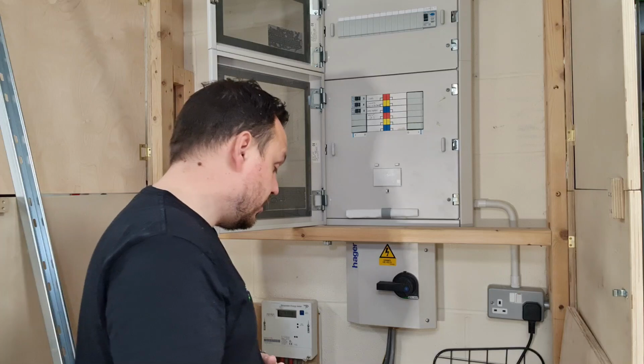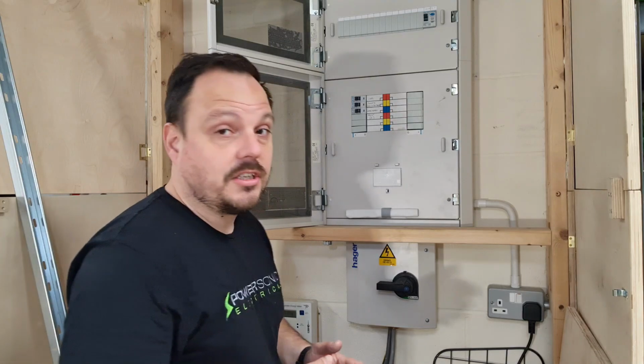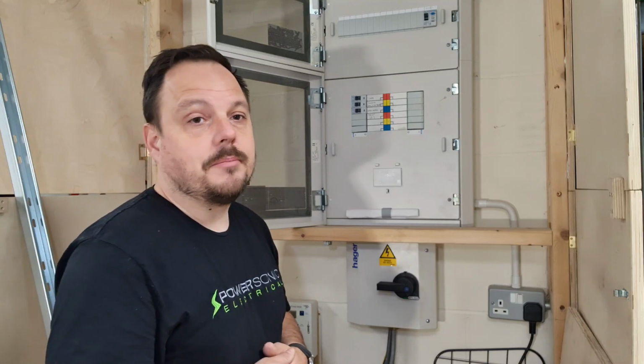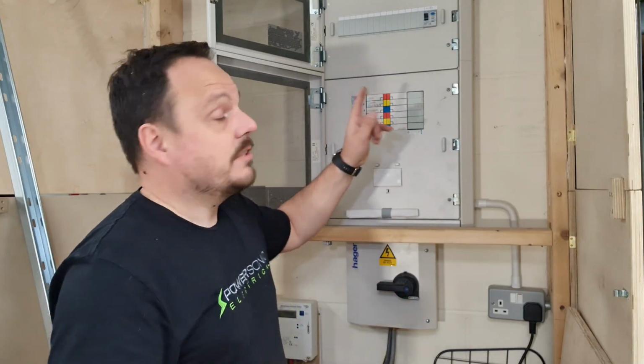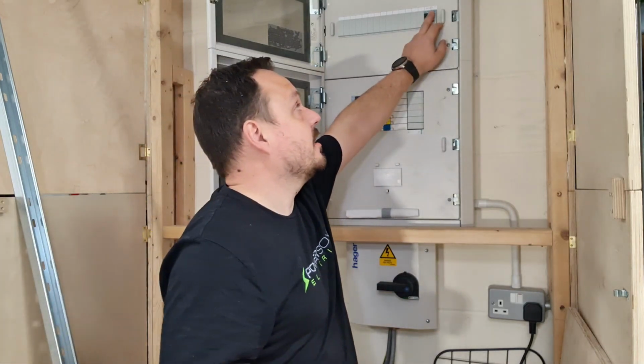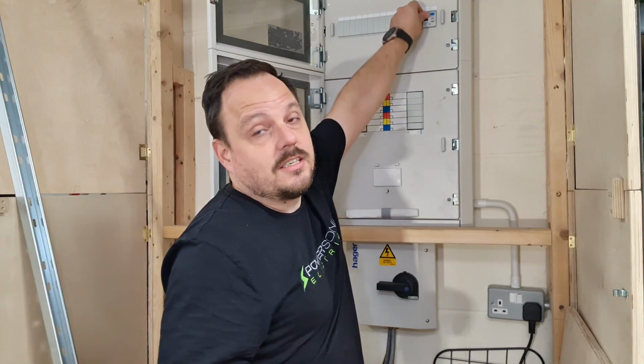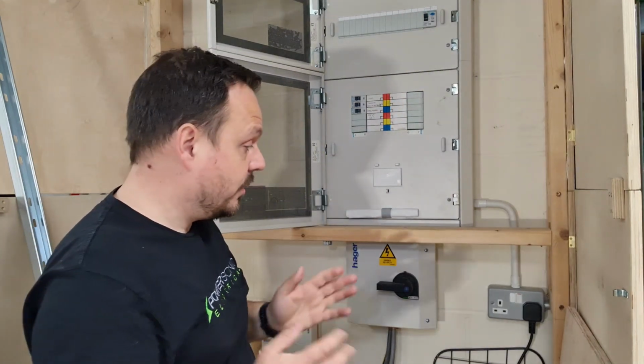So that's not to sniff your nose at, and I've measured this dip above sort of 10 to 15 milliamps. Obviously I've not got any of the computers switched back on or anything like that. Basically the only thing that's running right now is the router for the internet and the telephones. Everything else is off. So I suspect as I turn things back on, that would creep back up again. And the interesting thing I've observed is every time I press the test button on this, it's been operating. If I do the RCD tests on it, it works just fine.